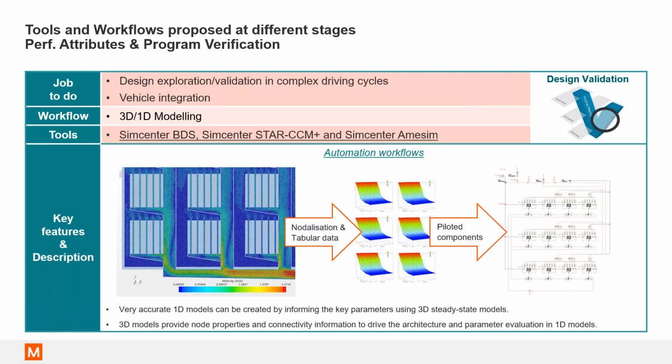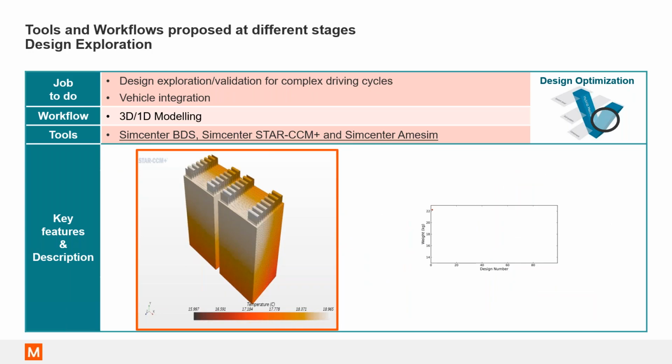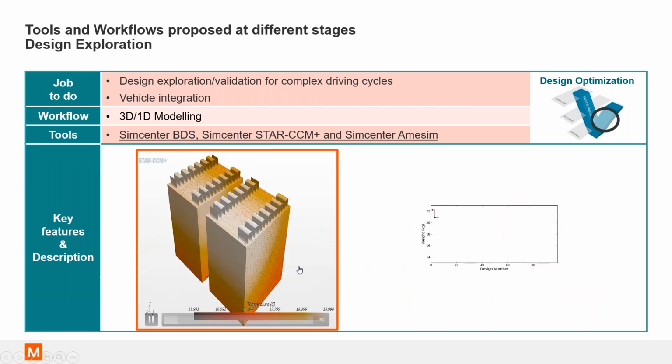And then I want to do a design validation of my whole performance attributes, right? And I want to explore how it would behave at the vehicle integration level. So effects of velocity or effects of water flowing through the coolant path. And I can get varying surface area maps for different load points, and using that, I could create that 1D model for different attributes that I'm looking for. I could also extend that to my pack level analysis.